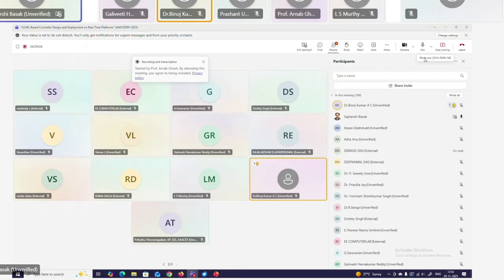If you go for stator flux or air gap flux, then you will not be able to achieve decoupled control over the torque and the flux. The DC machine like performance you will not be able to achieve.